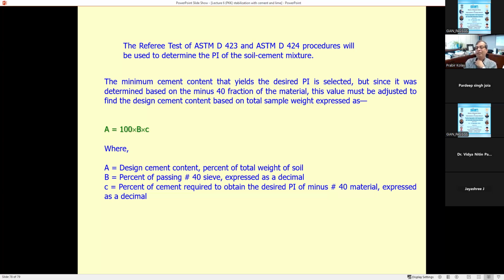Whatever test you do, such as the expansion index test or any other test, first, as I mentioned, the density: as seen in the standard Proctor graph, the lime decreases the density and the optimum moisture content basically increases. But when you prepare the soil sample, with time, it will be fine. Sometimes pure lime is not going to help, so sometimes you need to add some other stabilizer also.